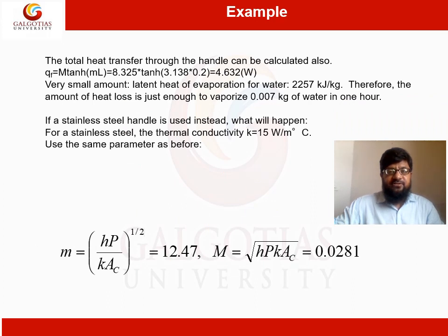The total heat transfer through the handle can be calculated by using the formula, which comes to 4.632 watts. So it is a very small amount. The amount of heat loss is just enough to vaporize 0.007 kg of water in 1 hour.